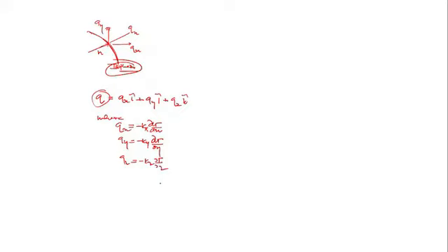Okay? So in short we can write q as q_x, minus k_x into del T upon del x. Flux I am going to write here: minus k_y into del T upon del y, plus minus k_z into del T upon del z.